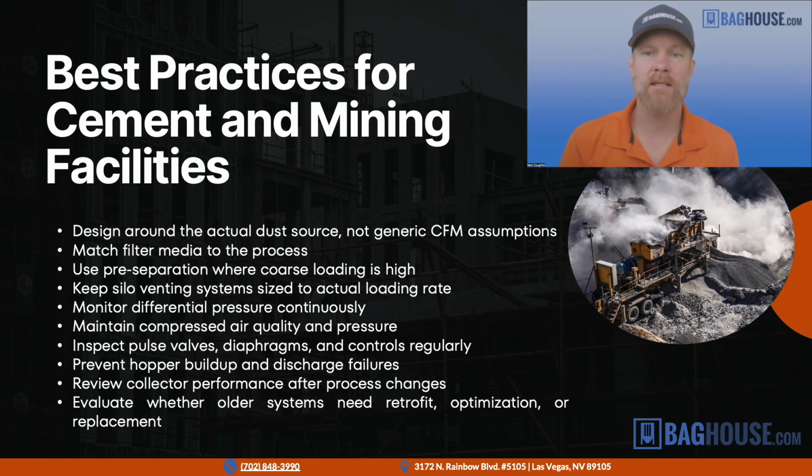The processes connected to the dust collection system may have changed. So, if you're looking to retrofit a system, optimize it, you may need to go back to the drawing board to make sure that the sizing, the vent, capture, vent design, and all these things we talked about may need to be reevaluated to make sure that that system is properly designed for the current state application.